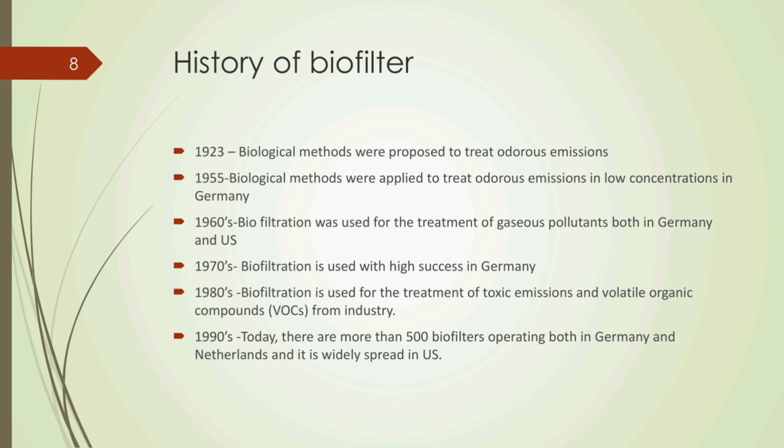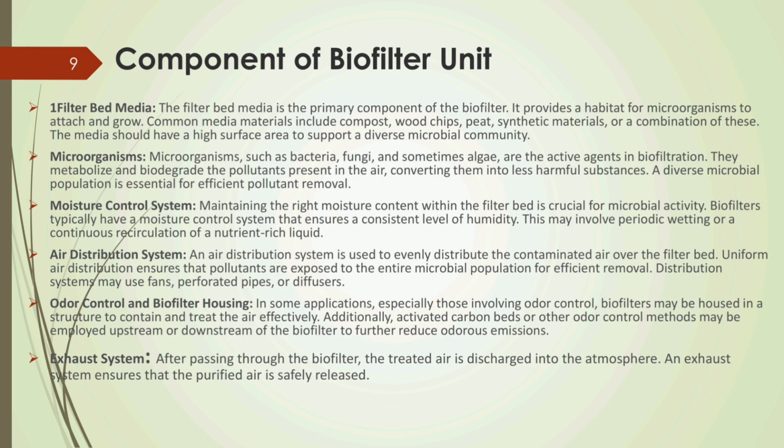Component of biofilter unit: filter bed media. Filter bed media included compost, wood chips, peat, synthetic material, or combination of these for the habitat of microorganisms. Microorganisms such as bacteria, fungi, and sometimes algae are the active agent in biofiltration. They metabolize and biodegrade the pollutant present in the air, converting them into less harmful substance.